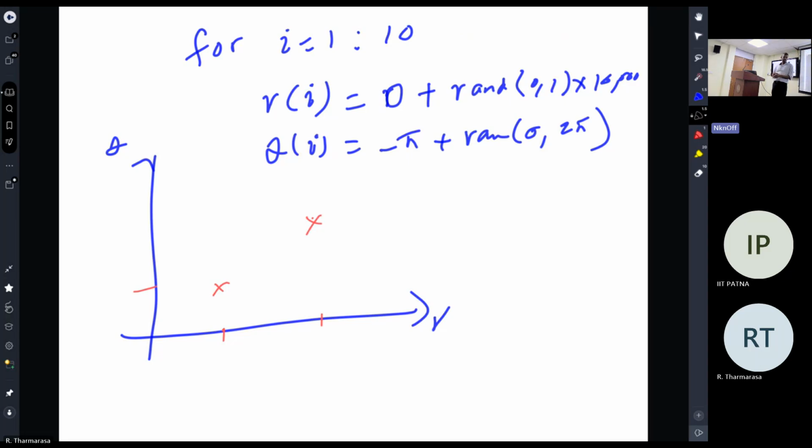But if I give more weight to the prior, then it will be somewhere here. So when you have a smaller process noise, you give a little more weight towards the prior, right? You trust the prior more compared to the measurement, correct? But if the exact noise is known, you always go with that. But I'm saying that if you can tune that, basically you are deciding whether to go with the measurement or not. That's what I said.